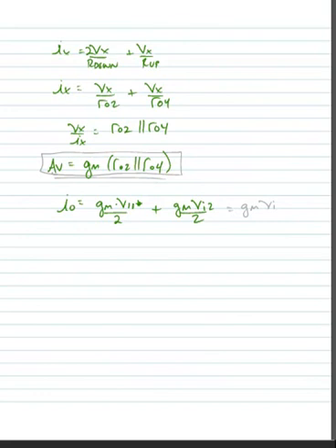Since the magnitude of the input voltages is equal, the swing is just opposite, so we could say that I out is equal to GM times VI. In other words, our total GM is just equal to GM, not GM over 2. Another way of putting that is we can do superposition to find the total GM.